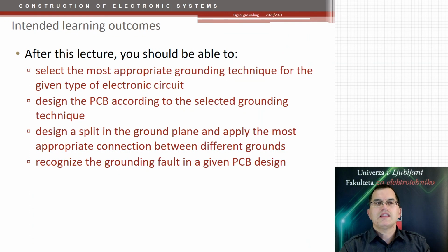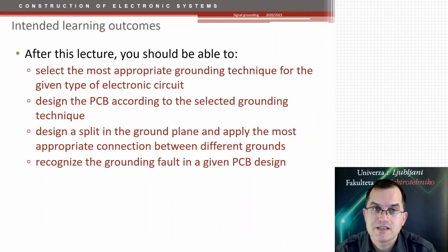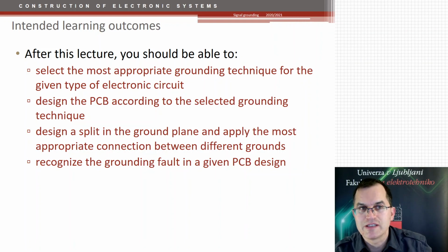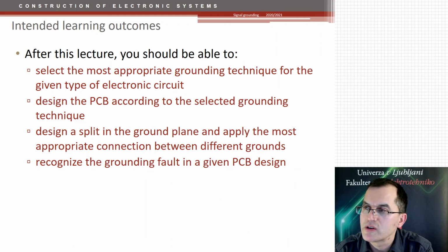Okay, by that I would like to finish. After this lecture, you should be able to select the most appropriate grounding technique. So for analog low frequency currents, we have star connection. For digital currents, we have multi-point connection and the solid ground plane. You should be able to design the PCB layout according to that.